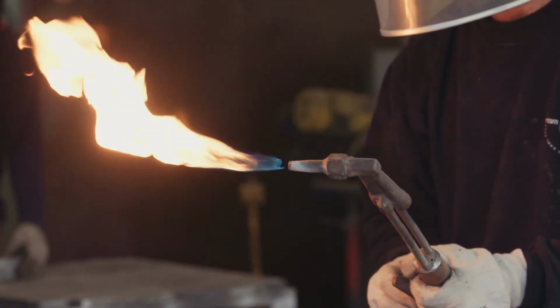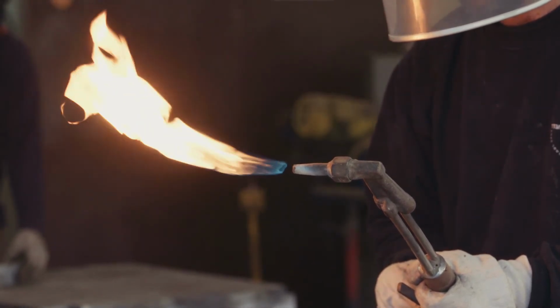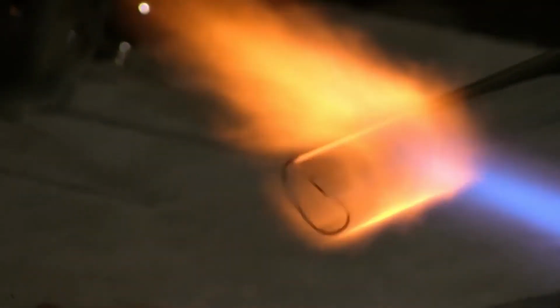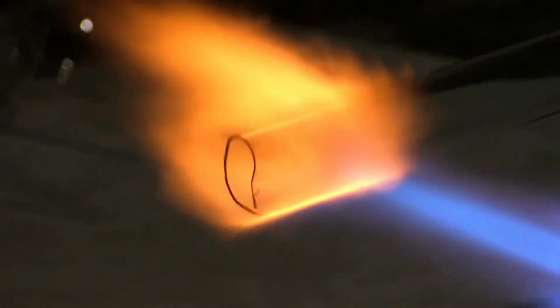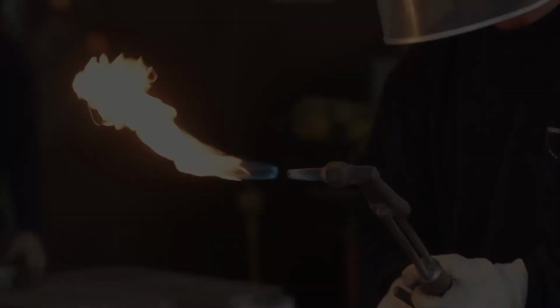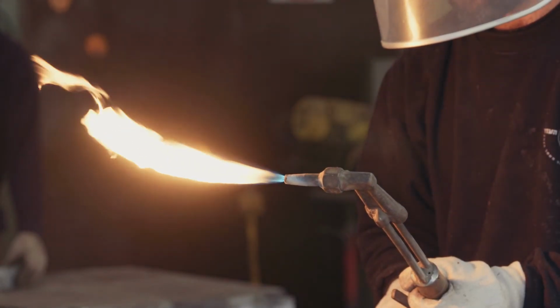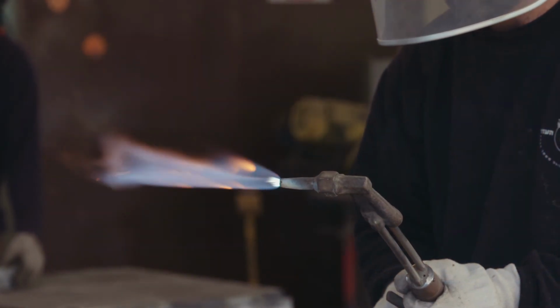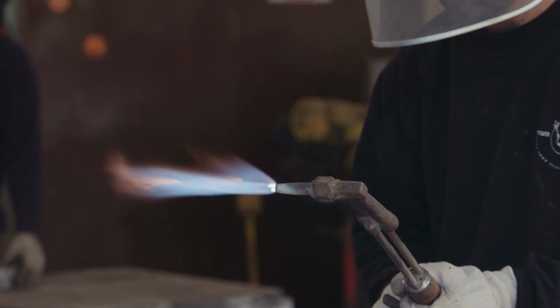In a neutral flame, there is no chemical reaction on the metal which is under operation. The materials that can be welded by using this type of welding flame are mild steel, stainless steel, cast iron, aluminum, and copper. Adjustment of a flame is crucial not only for the material welding process, but also for preheating in cutting operations. A great benefit of using this flame is that you get quite a clearer metal puddle that flows and gets removed quickly without any foaming and sparking.